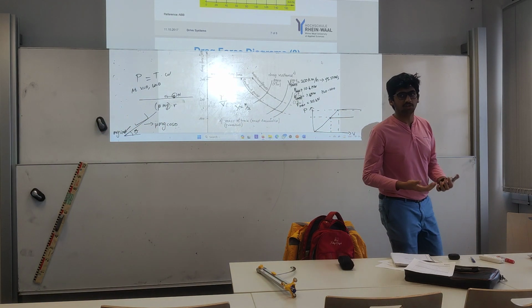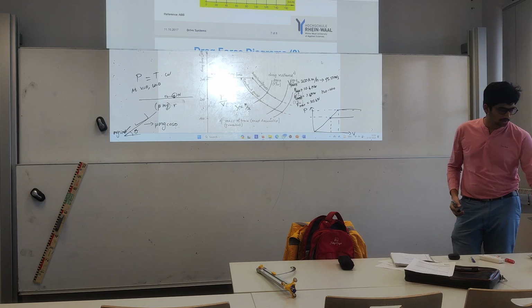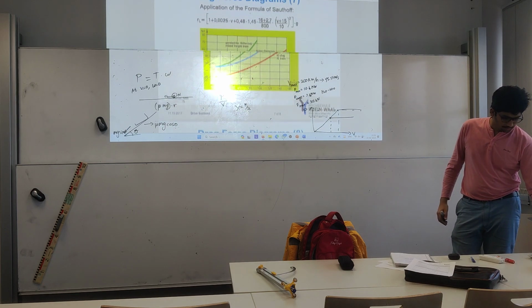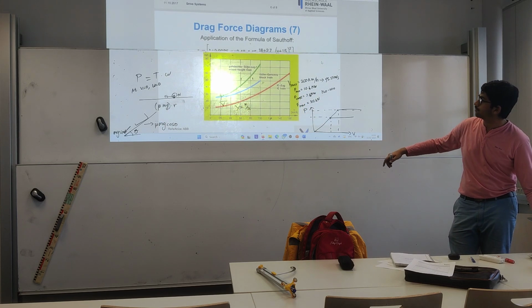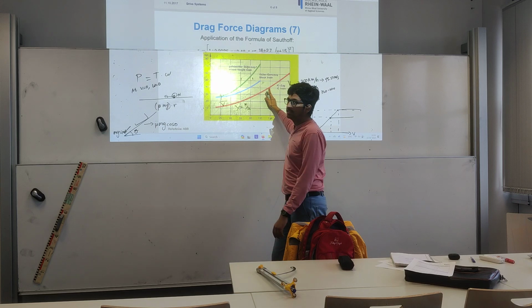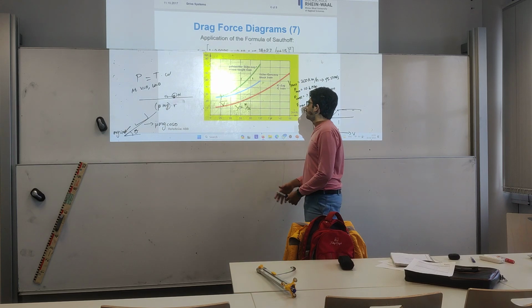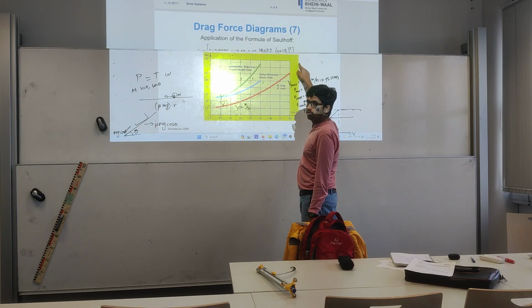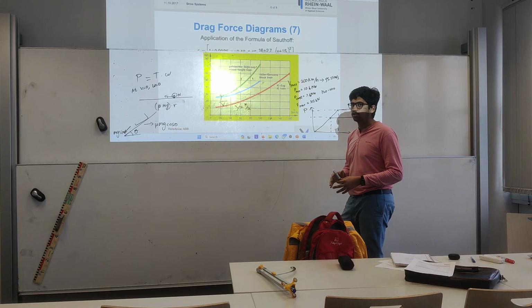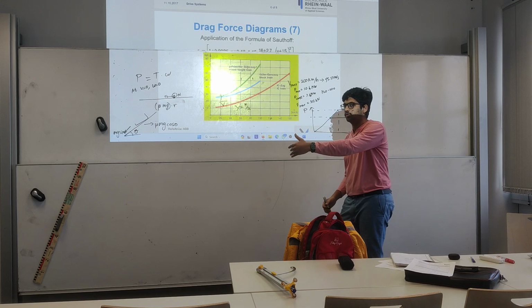Passenger train is focusing on speed, the mass is much lower, so this maximum drag force is not the focus for you. That's what is shown here. Look at the IC train, at any speed it needs a lesser force because it weighs lesser, but it's going to go to a higher speed, so you just change the gear ratio. With the same motor power, you just change the gear ratio for lower torque and a higher top speed.